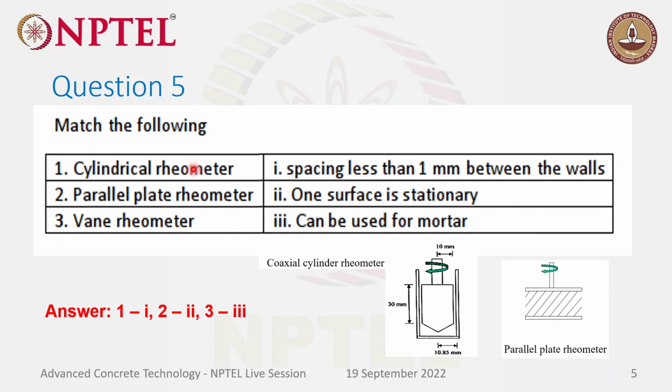Coming to the vane rheometer, we have used this vane shear apparatus for measuring the shear stress in clays in the soil geotech lab. It can be used to measure rheology for cement mortars.